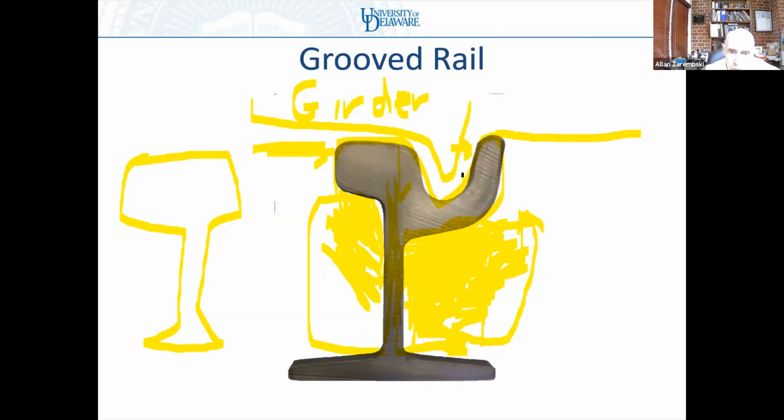The primary reason for having girder rail as opposed to T-rail is to give you the flangeway for the wheel. There are some metros out there that use T-rail and then introduce a strap, which is bolted through the web of the rail, and they've introduced a flangeway that way.